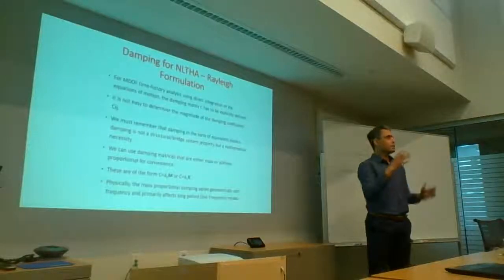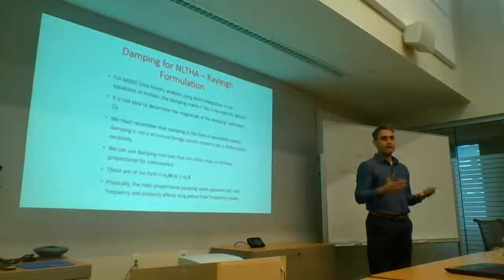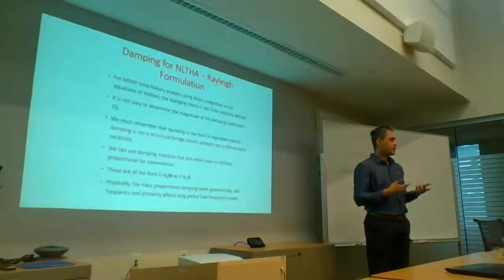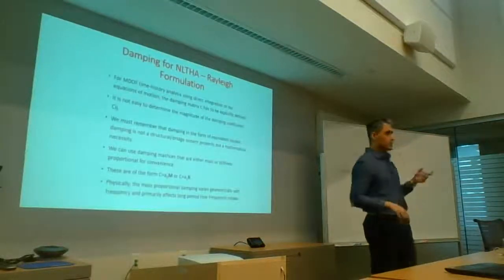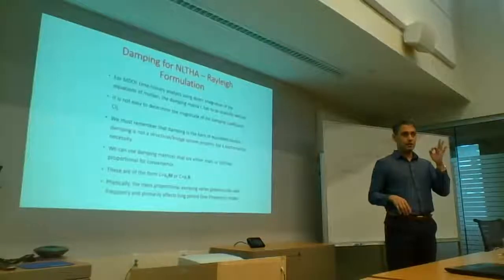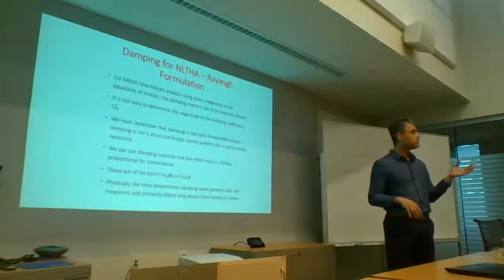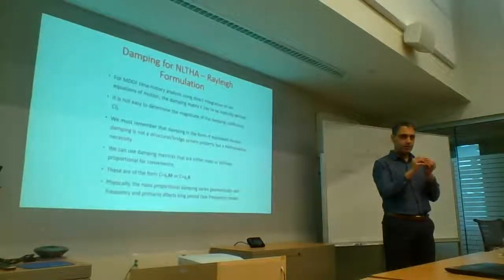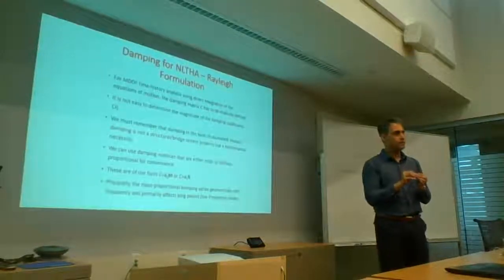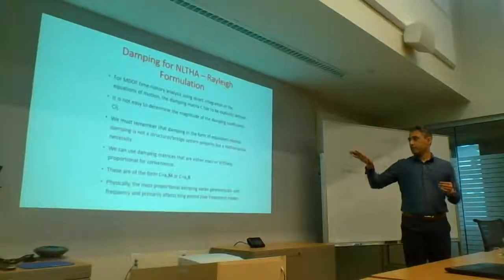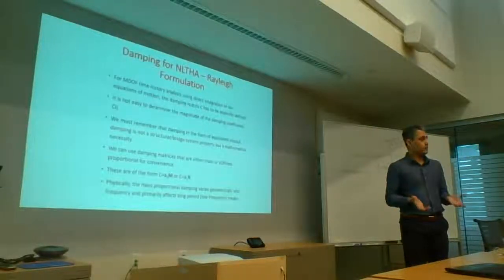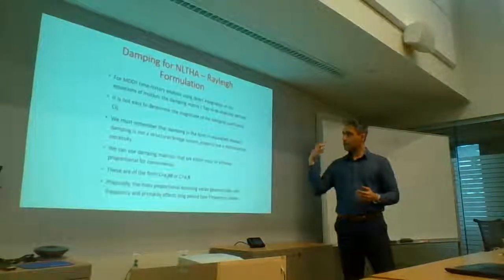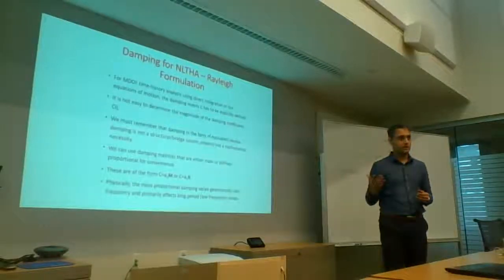The damping really comes from opening and closing of the cracks, from non-structural elements, from all of that heat and friction that occur, because concrete is going to crack very early on. As we know, the f cracking is only about 0.4 root f'c. So even though we think they're linear, things start to have some nonlinearity very early on. So viscous damping is a property of a fluid, not that of a structure, not of a solid thing. But it's a mathematical necessity, for mathematical ease. Okay.